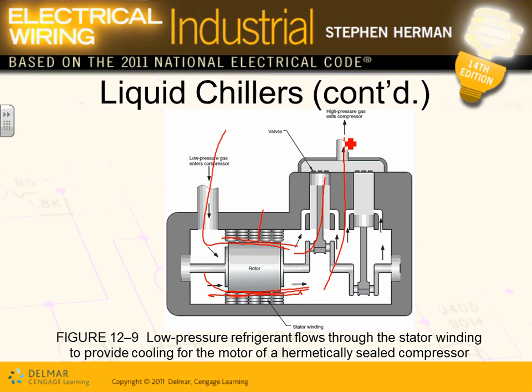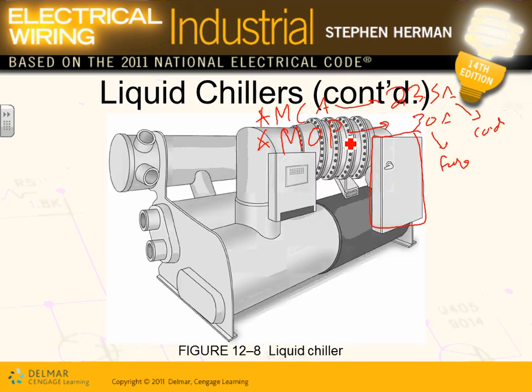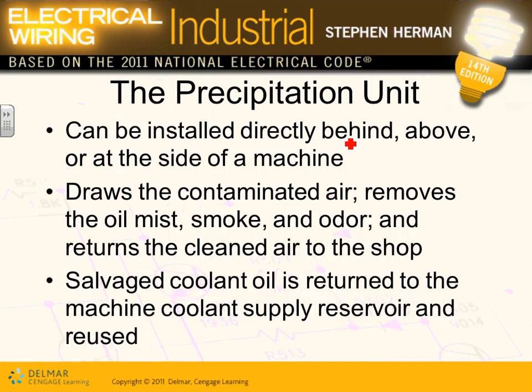And I have a presentation, guys, about cooling in a commercial building. We'll go over that one. Okay, so that's basically it. The only thing you really need to know is the minimum circuit ampacity and the maximum overcurrent protection device for motors. You guys have done calculations with me before for this.